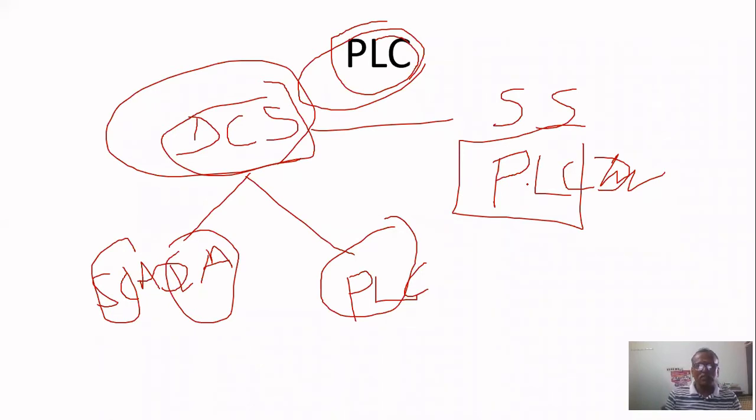Once the temperature rises to some level, then gradually they will feed the pulverized lignite inside the furnace, and gradually they will close the liquid fuel, and once the temperature is reached, they will operate by using lignite. These are all sequence of operation, not closed loop analog control.